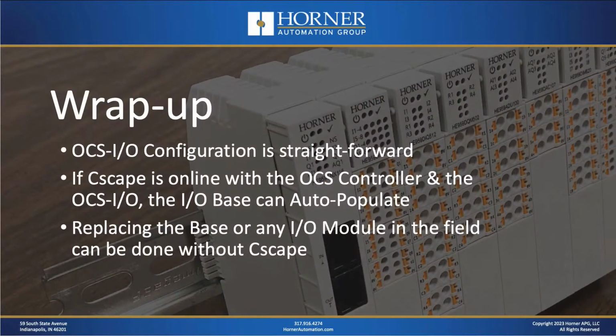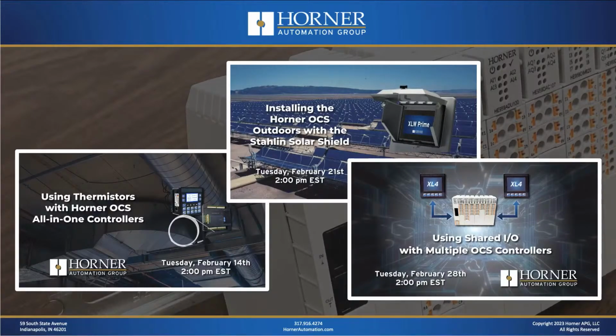That's it for our topic for today. Let's wrap it up. OCS-IO configuration is a straightforward process. If Cscape is online with your OCS controller and the OCS-IO, then the IO base can be auto-populated in Cscape, which can save you a little bit of time. If ever in the future you need to replace a base for any reason or an IO module in the field for any reason, both of those tasks can be done without any Cscape intervention whatsoever, even on a multiple base system.